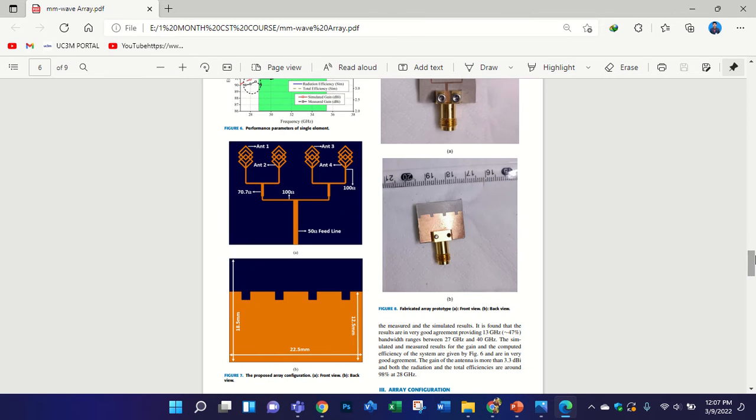Yes, but the main thing is that in the antenna, when you have here a 50 ohm feed line, okay, and you have set the impedance at 50 ohm, and for example you have a lambda of this feed line, and then you need to convert it into lambda by 2, okay. You need to divide your feed line into, they have used a 4 element antenna array, okay, and you can see here all of this, this stub and this stub, and this length and width, this length and width are of the same size, okay.